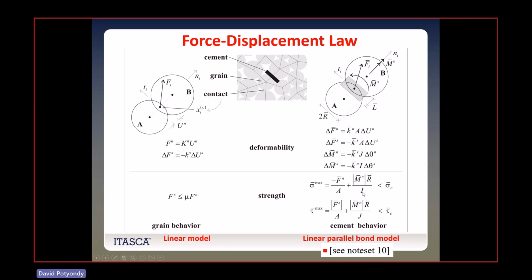This is the moment of inertia. There's also going to be a component which is just the pulling force, the axial force. So take that axial force divided by the cross-sectional area, add these two together, that's the outer fiber stress. And so we look at the worst case outer fiber stress, and we say if it's bigger than the strength, which will be the tensile strength, you'll break.